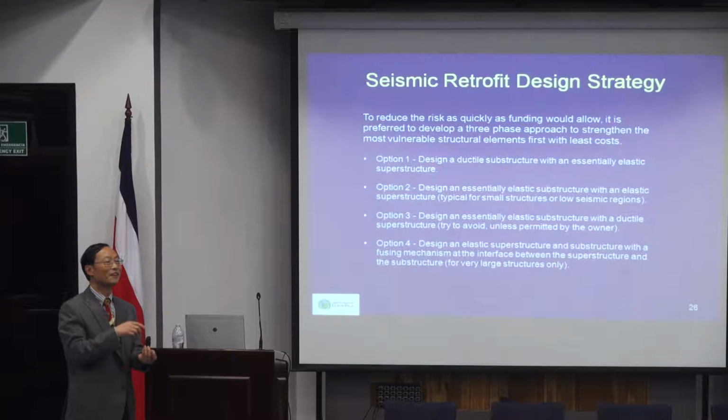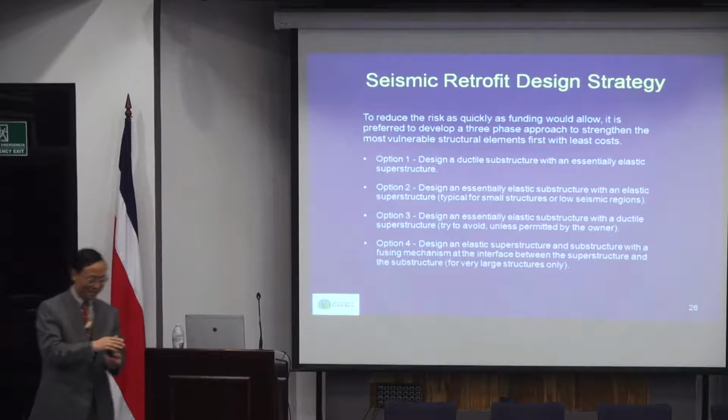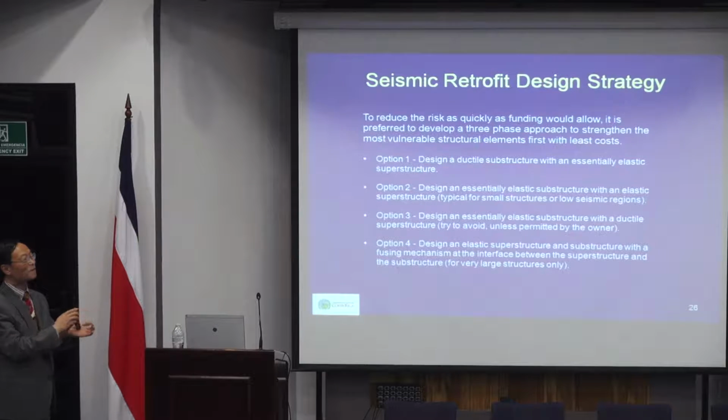Then I can design accordingly. But you have to make sure that with these assumptions, the bridge foundation and your column have sufficient ductility, otherwise if you move a little bit, it crashes, and then it will not work.